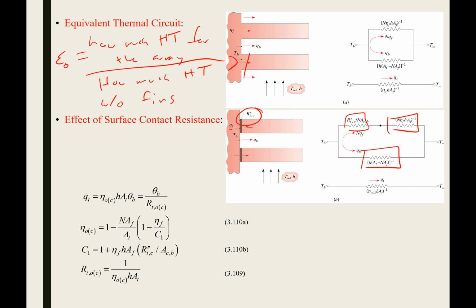Okay, so hopefully these definitions and that table will really help you on your homework problem number 1 for this week. You're given an array of fins, and first I ask you to go through and figure out all these parameters for a single fin. So you need to solve for the temperature distribution, which should just be plug and chug from equations from that table. Then you would calculate the total amount of heat transfer from that fin. Then we look at analyzing the entire array.